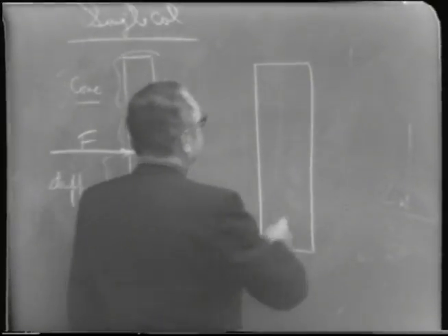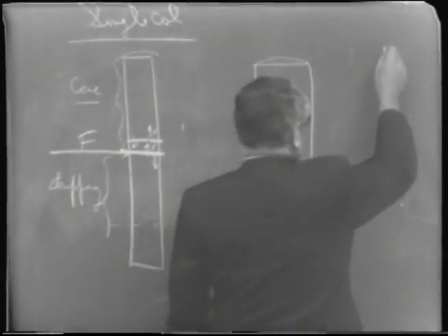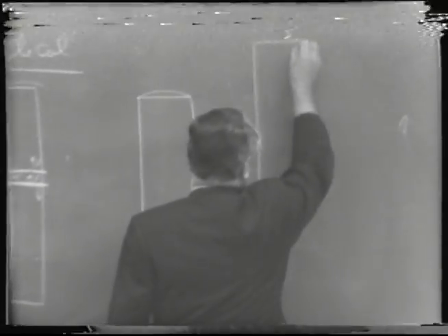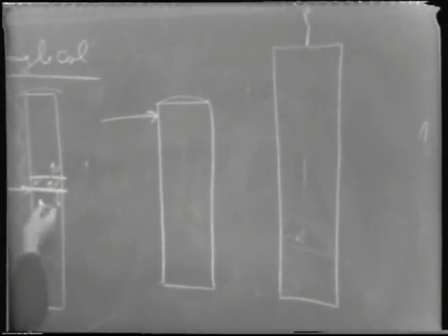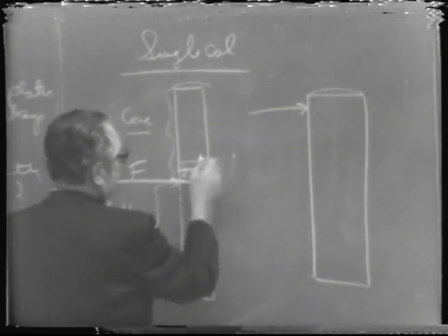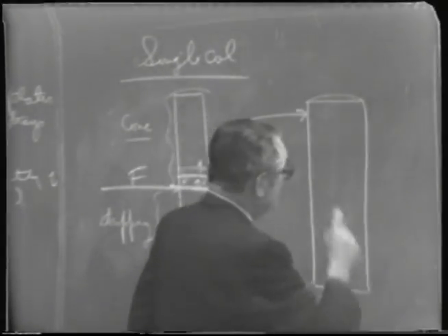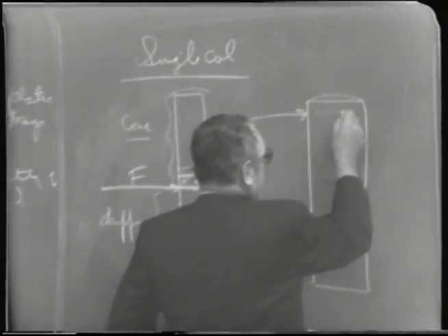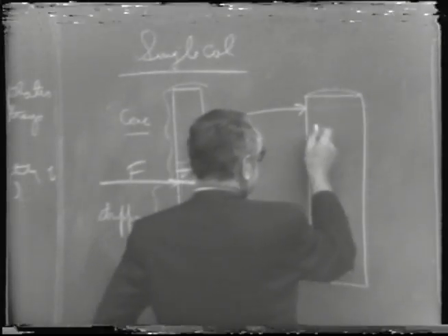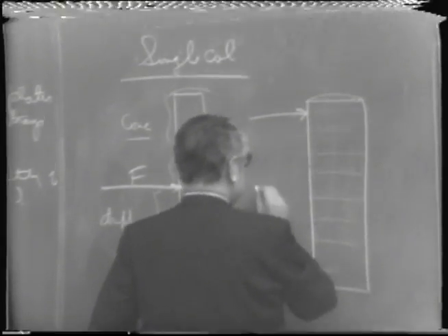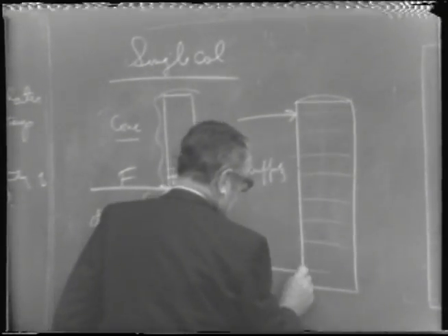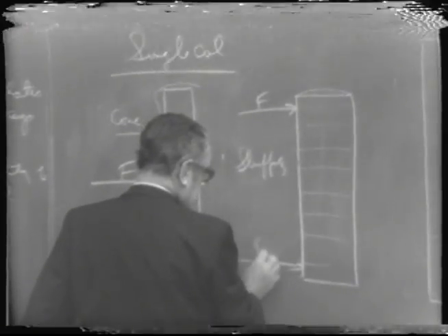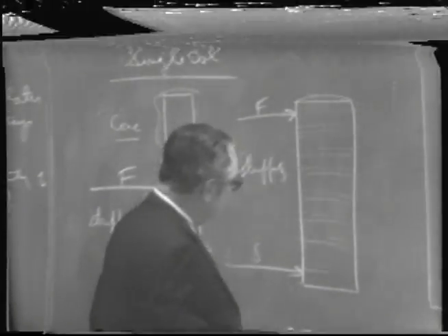let's draw this a little bigger, is to put the two alongside each other. And so here we'd have the feed up near the top. It might be actually split, not right at this point, but at about here, 2 or 3 trays above sometimes they put it above the feed point, but it can be exactly right at the top. So this is the stripping section, with, of course, the feed going in here, and steam, if it's direct steam heating